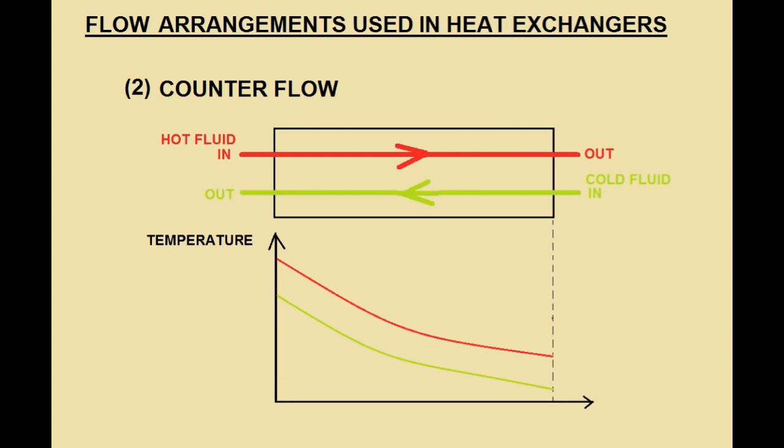More uniform temperature difference produces a more uniform rate of heat transfer throughout the heat exchanger. If the heat exchanger is well designed, the outlet temperature of the cold side can even be higher than the outlet temperature of the hot side.